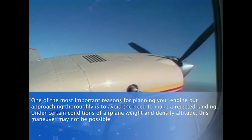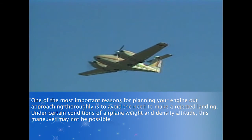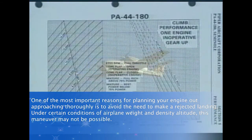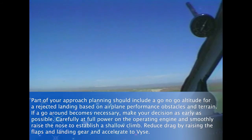One of the most important reasons for planning your engine-out approach thoroughly is to avoid the need to make a rejected landing. Under certain conditions of airplane weight and density altitude, this maneuver may not be possible. Part of your approach planning should include a go, no-go altitude for a rejected landing based on airplane performance, obstacles, and terrain. If a go-around becomes necessary, make your decision as early as possible.